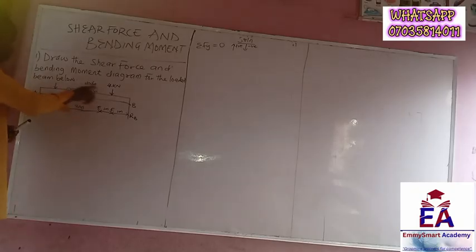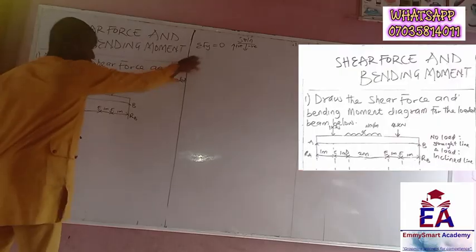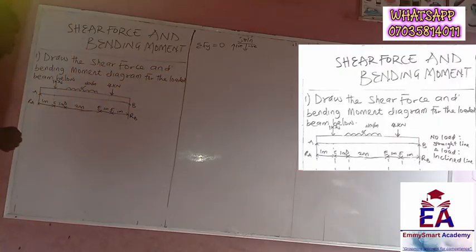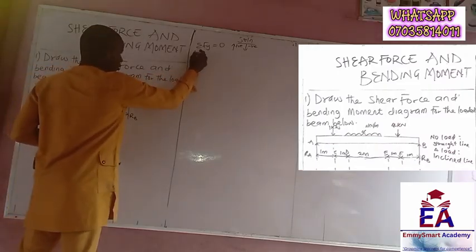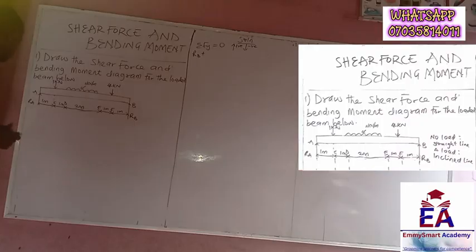Then you see a beam here, a distributed load here, and then we have point loads at several ends of the beam. So here is 1 kilonewton. Okay, so the first thing we need to do, remember we said summation of all vertical forces equals 0. Right, the vertical forces we have: R_B, reaction at B, is one of the forces, plus